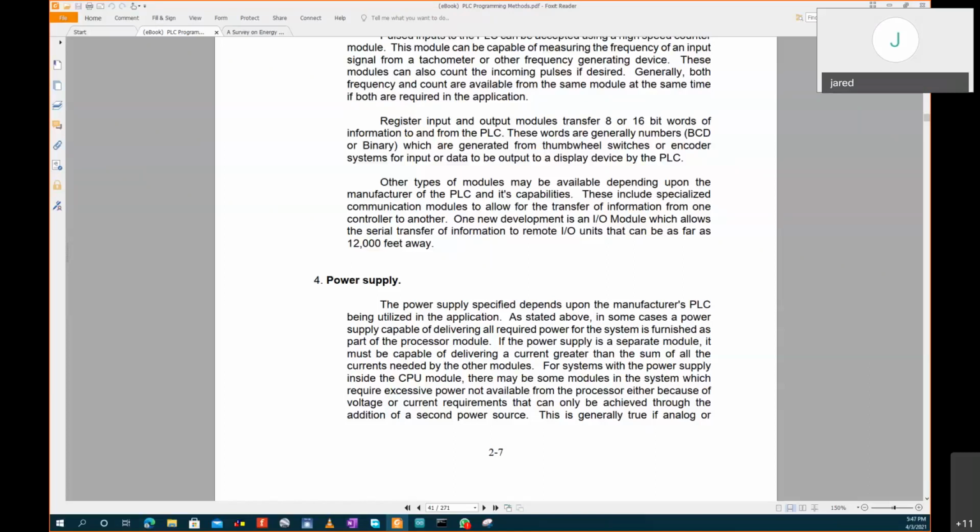For industry PLCs, because you cannot stop a full factory from running when you want to change a module. So they are made in a way that, the same way you can plug in a mouse and plug it back, or you plug in a flash disk and unplug it, that's hot swapping. So even for the modular PLCs, you plug a module in and out, and you won't realize the difference. Your sensors will still be running, and you won't affect production on your end. So that's what we mean by that.